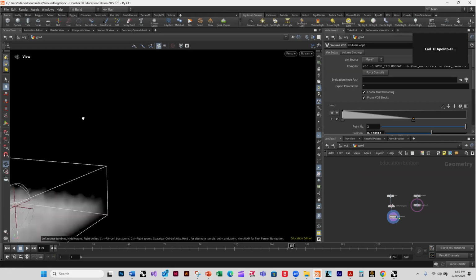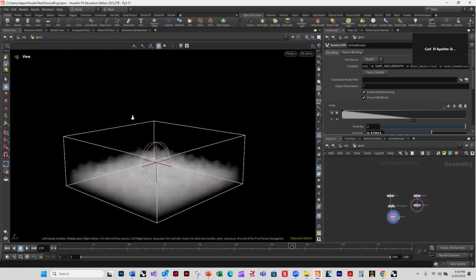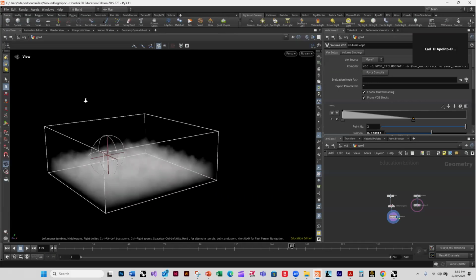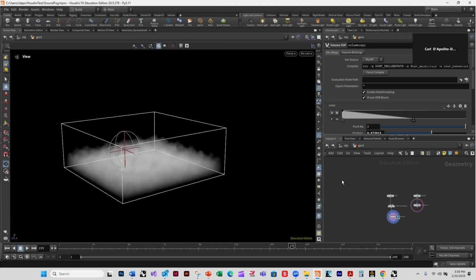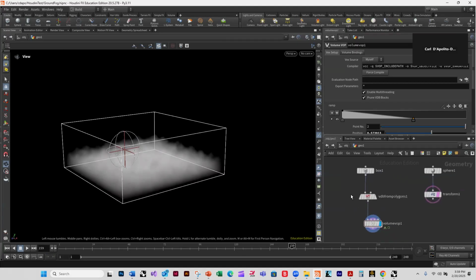It's Alt rather than whatever it is on Rhino that you have to use to do this stuff. Okay, so it's very annoying. It's Alt, middle, and pan. Okay, and then this is the main viewport window. This is the most important thing over here. This is the palette where you have all these nodes. Houdini is like long chains of nodes connected together. So it looks a lot like Grasshopper, but it's not at all the same. It's like long chains of nodes connected to each other.